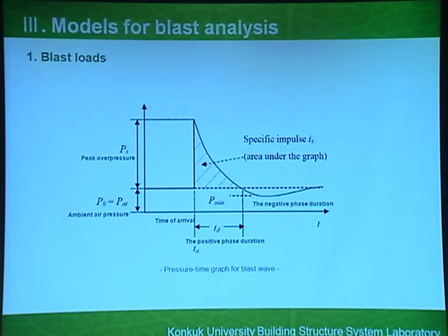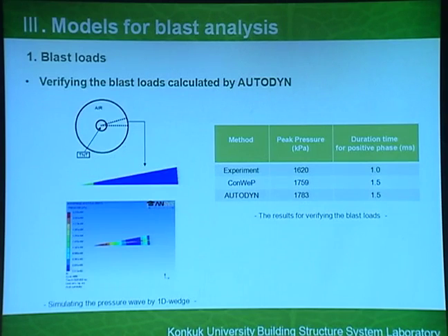Okay, this is a typical pressure of a blast. If a blast occurs, it generates a high positive pressure, and then some low negative pressure. If you want to simulate it with a numerical program, we have to simulate this kind of pressure distribution. AutoDyn provides a very efficient way to simulate a blast load, like the 1D wedge.